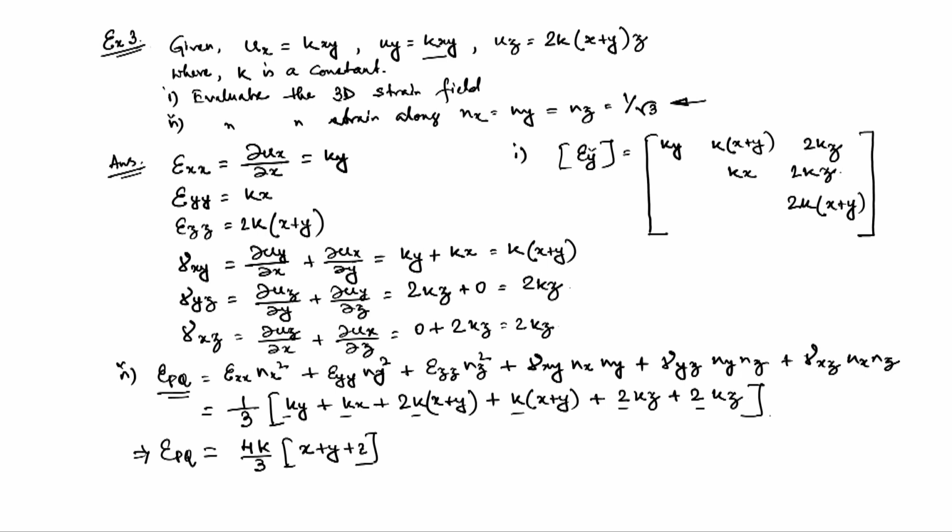As we progress, first we will solve some example for principal strain, and we will also see how to develop some compatibility conditions. That is most important, because once we are given the displacement field ux, uy, uz, we can find out the strain field. That is very easy, straightforward, because we need to basically differentiate the displacement field with respect to x, obviously for linear strain. But if we go for the reverse, that means once we are given these components of strain, and from there if we need to find out the displacement field, that is ux, uy, uz, then we need some additional criteria.